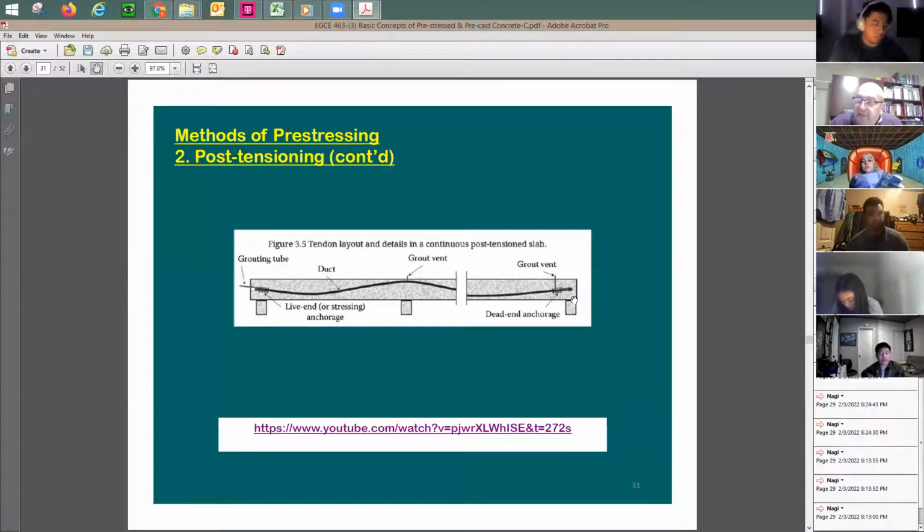So we have a question here. It says, does post-tensioning allow you to retension the tendons many years down the line after significant tension loss has occurred? Practically, not really. Especially in slabs, like building slabs, it's going to be really tough to get in there and do any tensioning. It's not going to happen. And in post-tension slabs, in many cases, we don't have the bond. But in big bridges, this could be important.